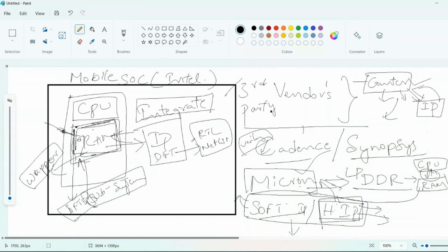So all the sensors, analog sensors. Your mobile phone has many sensors, right? Sensors, actuators, everything. Digital IPs, analog IPs. All of these are hard IPs. Anything that you cannot change, either a digital IP or an analog IP, is a hard IP. Even the memories: you are using RAM, ROM, all these memories inside your SoC.